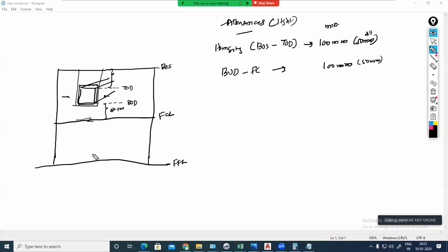Conductivity value we can find from this table in the insulation chapter. The required R value is also there with respect to the climate zone. If you know this K value and R value, the thickness of insulation we can easily find. That we can study in the insulation chapter. Anyhow, normally for inside a duct the maximum insulation will be 25 mm. That's the maximum for glass wool. Means 25 mm on the top side, 25 mm on the bottom side. 25, 25. So overall, how much? Thermal insulation, 50 mm. There is no other allowance for that.